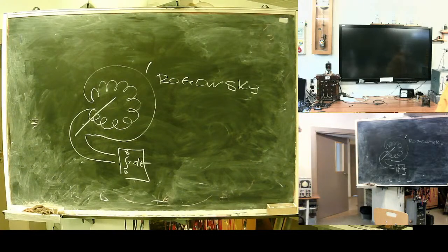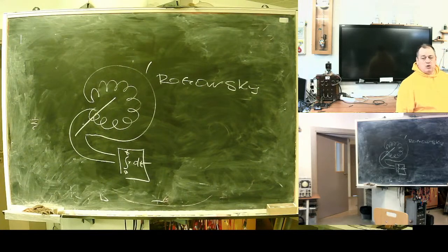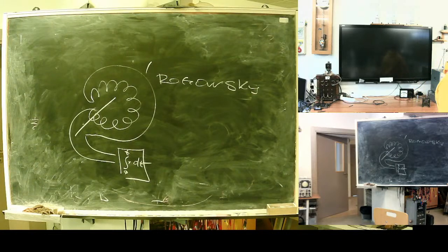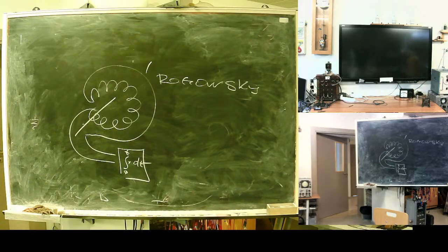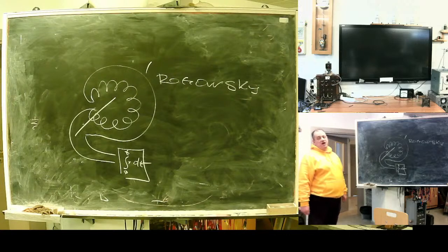You can easily understand you're dealing with a Rogowski coil by the output connector. Scopes have a coaxial output, a BNC connector, round with one central socket. Rogowski has a similar round connector, similar to BNC, but with two sockets inside. It's very typical for Rogowski sensors. A Rogowski coil gives out the first derivative of the current, not the current.